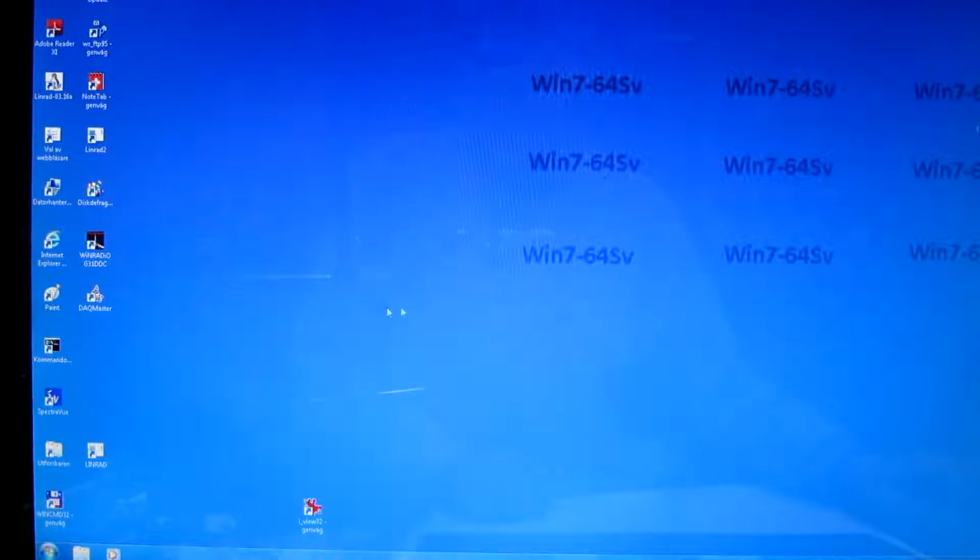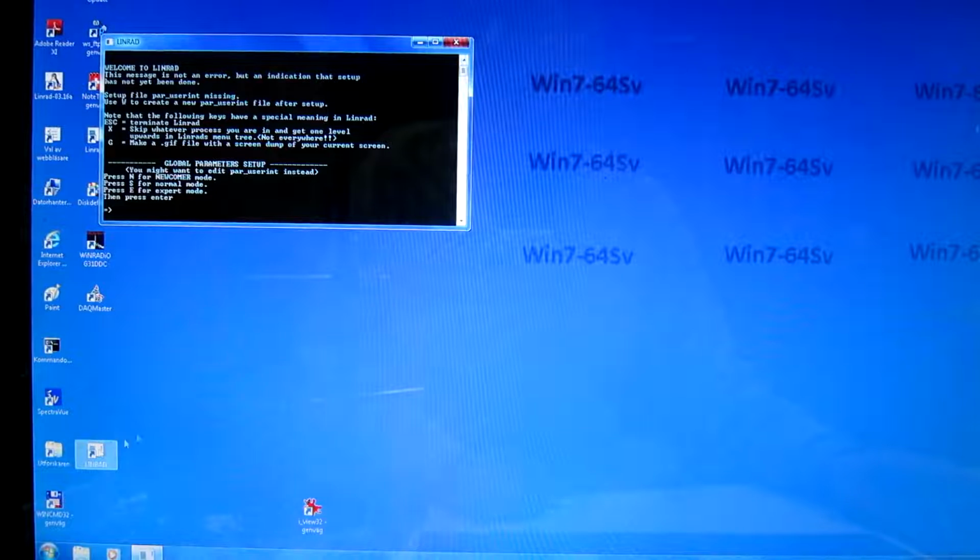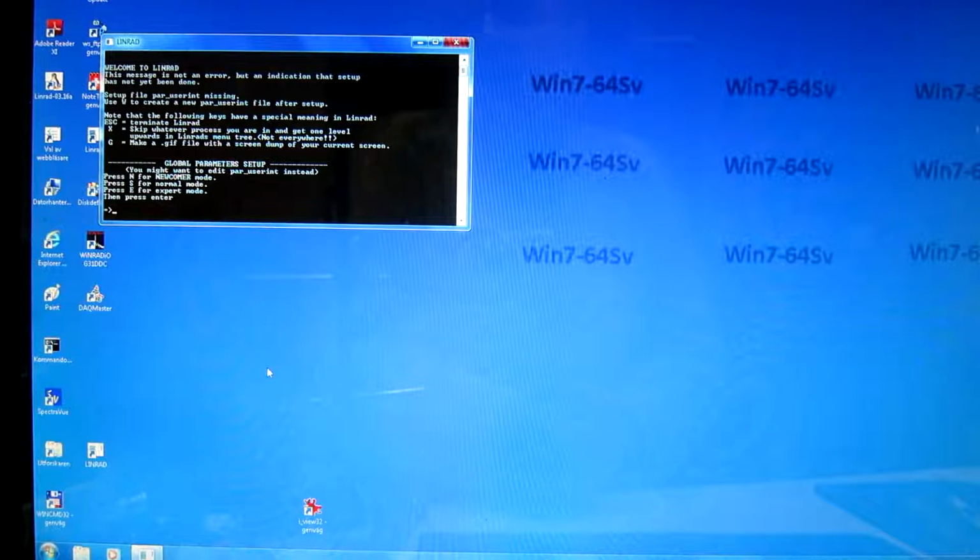The SDR-IP uses the network. There is no installation procedure for the hardware because the network is already in place. I start Linrad as an expert because I want to use the second time function oscilloscope to demonstrate how successful the calibration is in terms of making the blanker work well. Here I will calibrate with the function generator and then verify with the proper pulse generator.